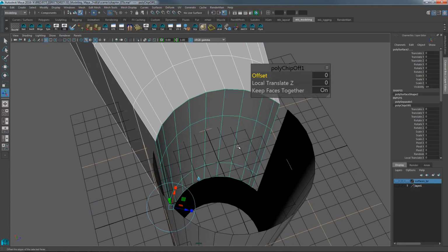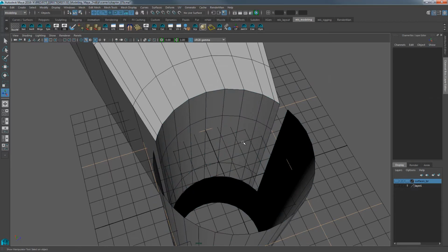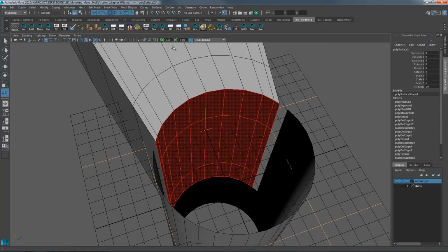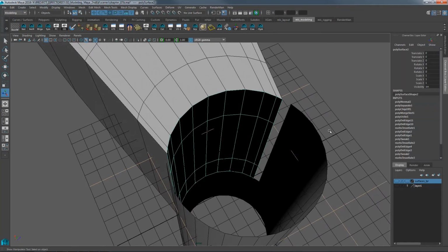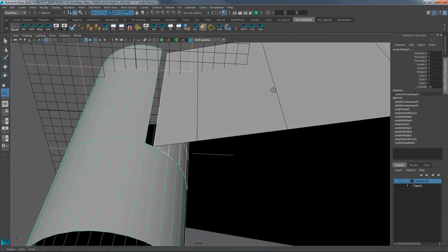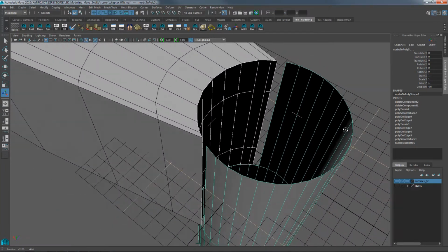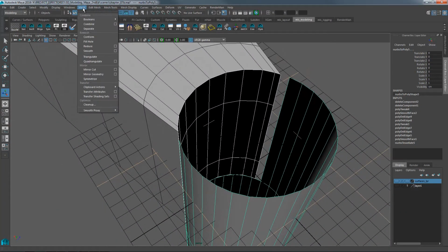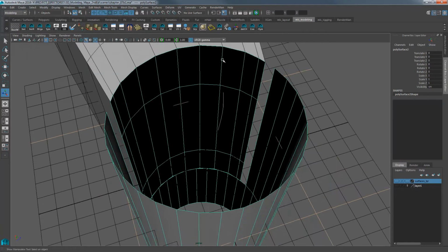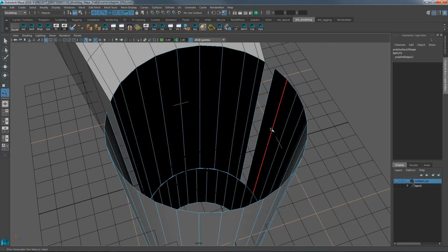Extract it. Okay, select it, this new object, this one object, flip it, reverse the surface direction. Take these two pieces and now bring those two pieces together into one object, combine. Delete construction history, remove this edge loop and that edge loop, Control Delete.